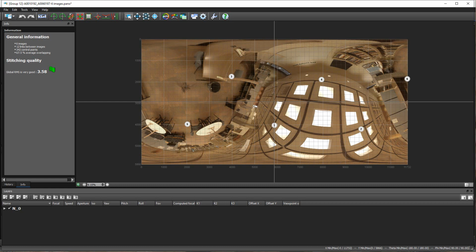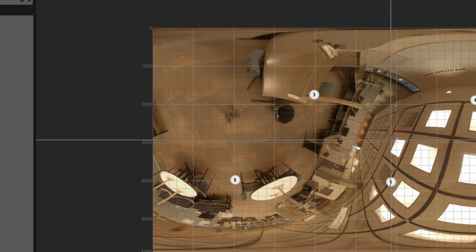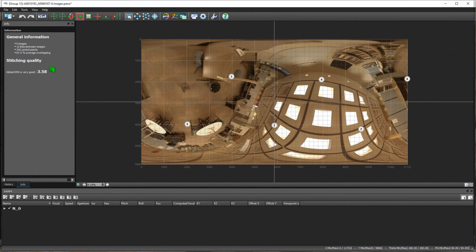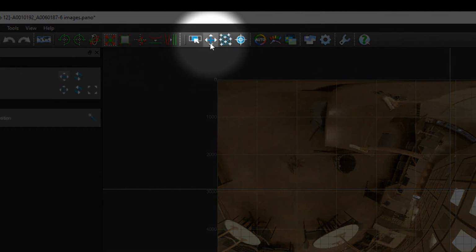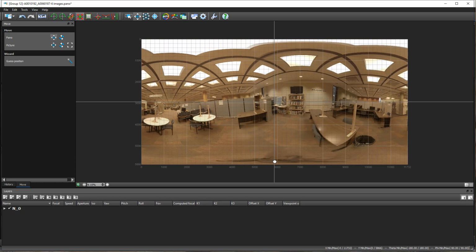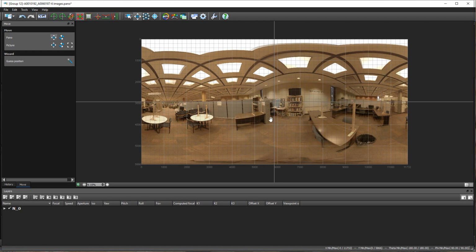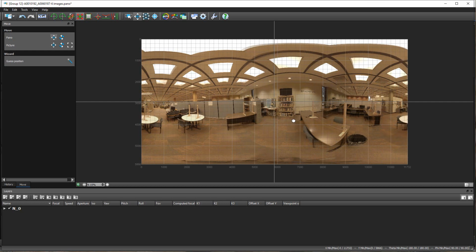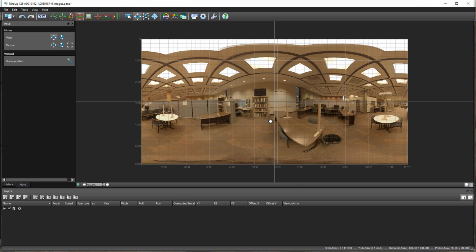The next thing that we're going to do is shift around all these images to orient the panoramic view the way we want. To do that, we'll have to identify a stable point and base everything else off of that. In this case, I will look at the tripod at the very bottom of the image. So we'll go up to the top, click Move Images, and then click and drag the overall image. Again, basing on that tripod as the bottom, I'm going to get that down and smoosh it to the bottom. Then this is where you can look at all those horizontal and vertical lines in the actual image: the brick patterns, the bookshelf, those partition walls. By looking at those vertical and horizontal lines, I can get the overall image mostly oriented so that it's like a proper view.